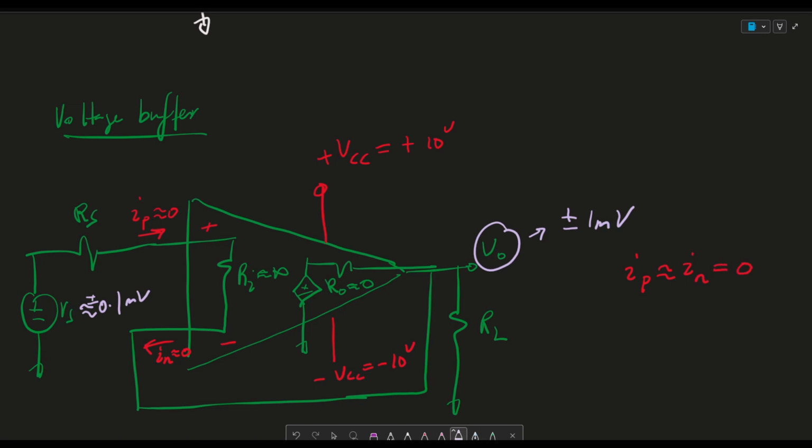And so then now the voltage here, let's call this voltage VP. All right. Since there's no current flowing through here, as a result of that, VN is equal to VP. If you can't see that, basically consider the voltage drop across this resistor.